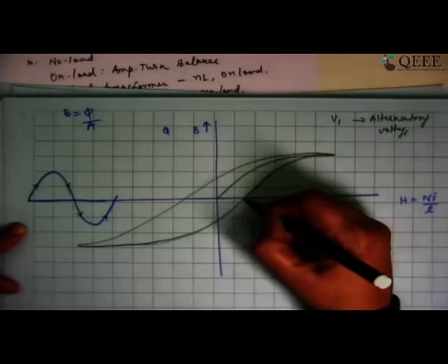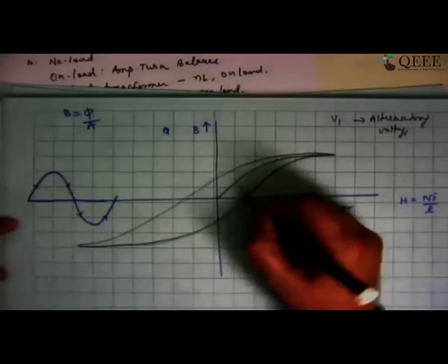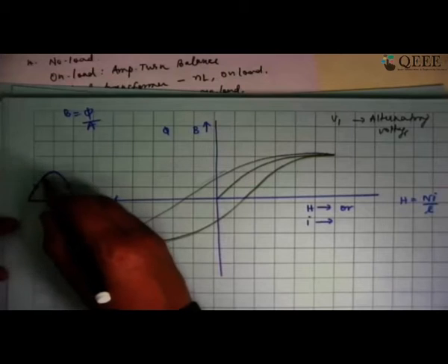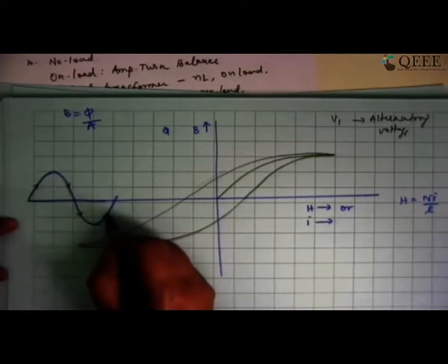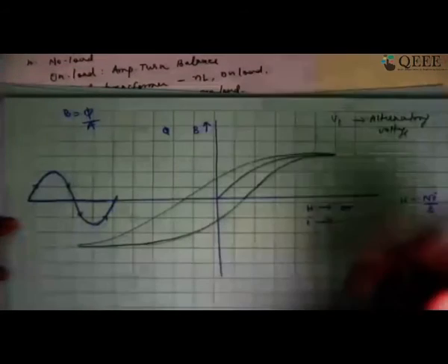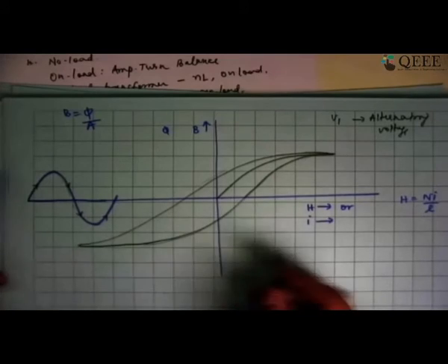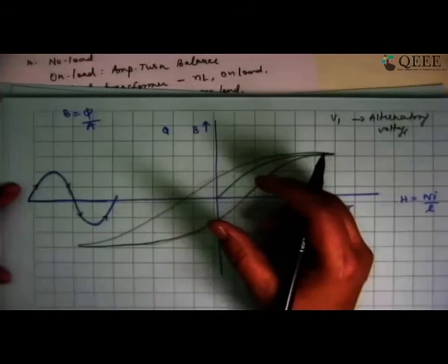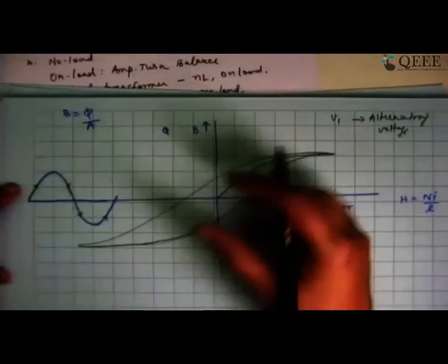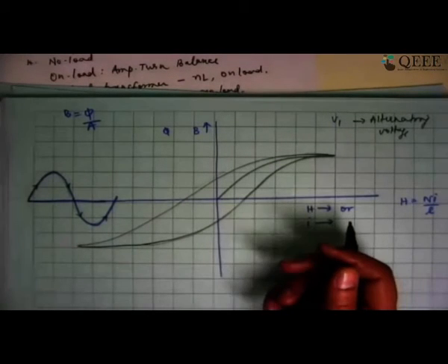Now, this aligning and realigning of the magnetic domains is repeatedly done when the current is increasing in the positive direction and decreasing in the negative direction, and then it is going again and again. The aligning and realigning of the magnetic domains involves the external current doing some work on these domains, and that is manifested in the form of loss.